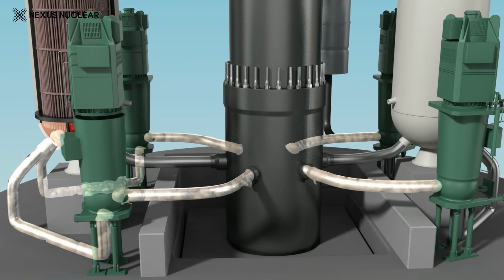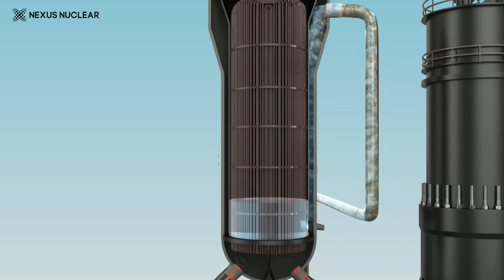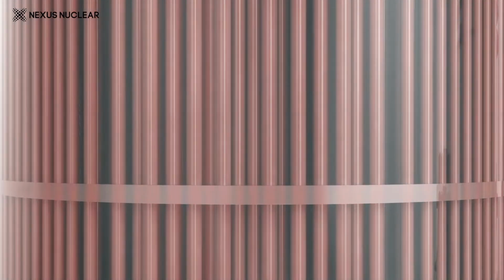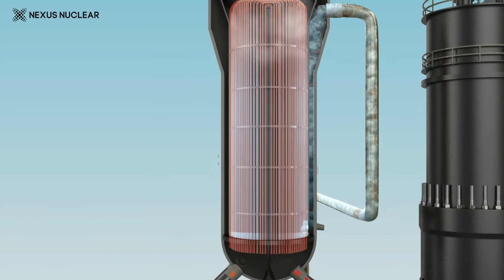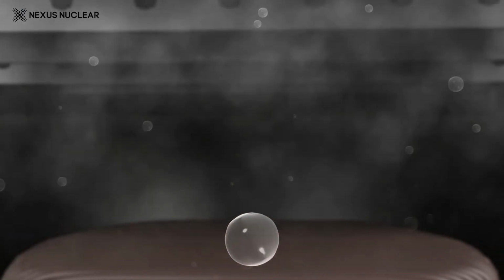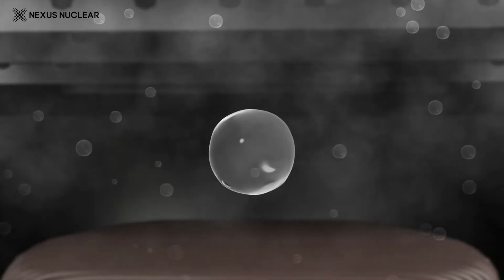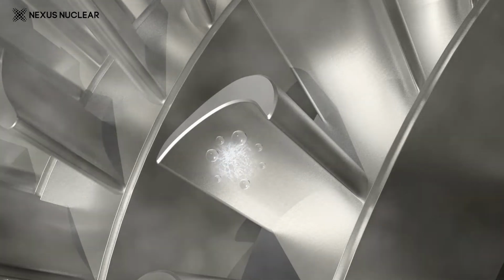Reactor coolant heated in the reactor moves through pipes to the steam generator. Hot reactor coolant flows through approximately 13,000 U-shaped tubes within the steam generator, making a full circuit as the 320 degree hot reactor coolant moves through the pipes. It heats feed water outside the pipes. The heated reactor coolant in the pipes cools down after transferring heat energy to the outside feed water and leaves through the rear pipes. This reactor coolant is then sent back to the reactor through the pipes.